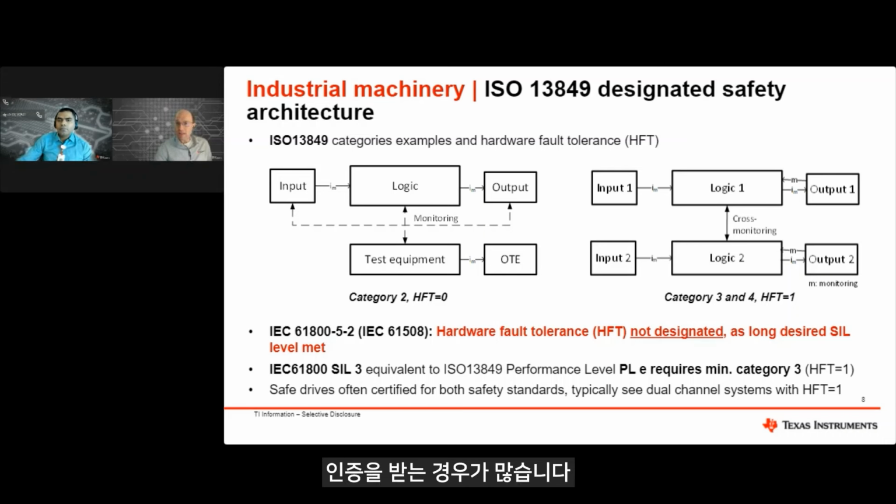Along with the FIT rate provided in the document, the probability of dangerous failures on demand per hour can be calculated too for this IC. This process needs to be continued for all components of the safe subsystem, of course.